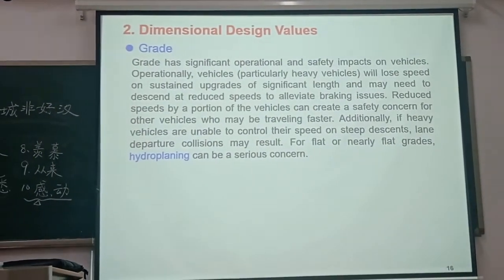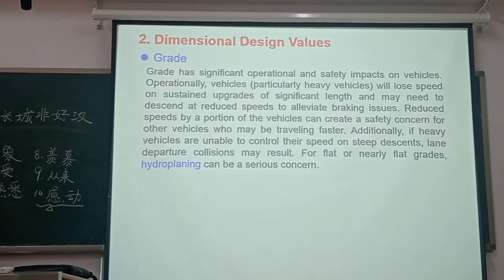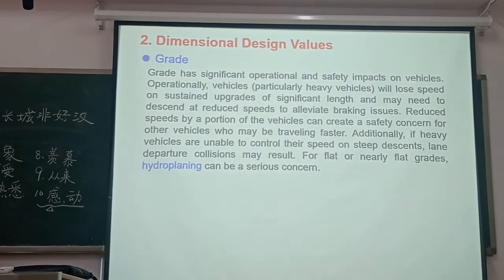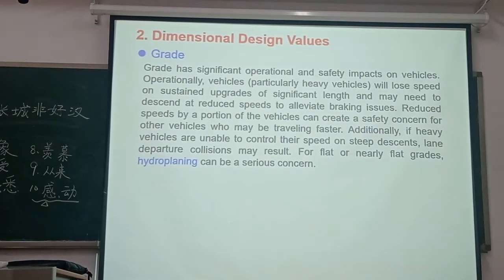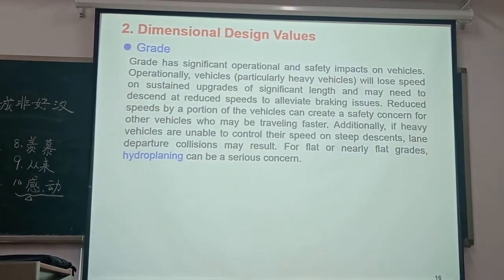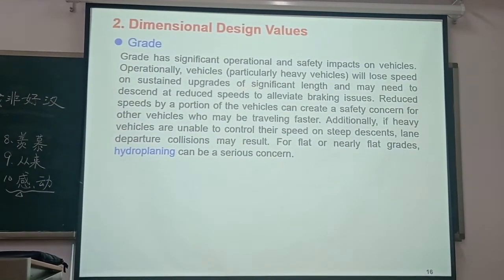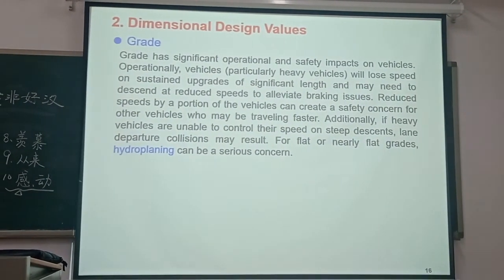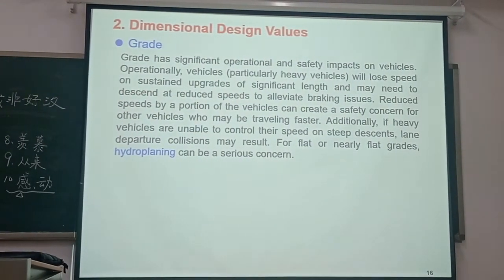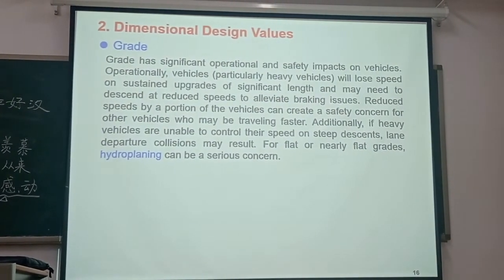Grade has significant operation and safety impact on vehicles. Operationally, vehicles, particularly heavy vehicles, will lose speed on sustained upgrades of significant length, and may need to descend and reduce the speed to alleviate braking issues.